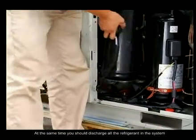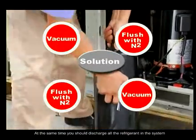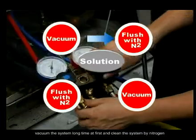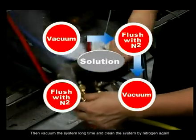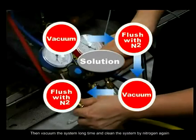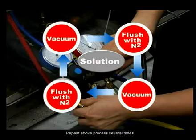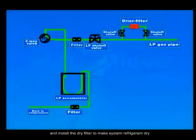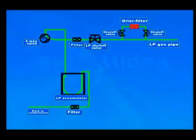At the same time, you should discharge all the refrigerant in the system. Vacuum the system for a long time at first and clean the system with nitrogen. Then vacuum the system for a long time and clean the system with nitrogen again. Repeat the above process several times. You can change all the refrigerant oil if necessary and install the dry filter to make the system refrigerant dry.